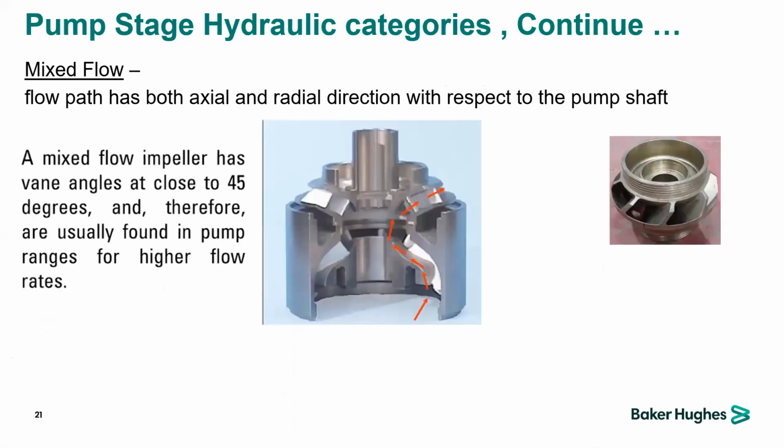Okay, with mixed flow, if you look at the pathway, it will be difficult to plug compared to radial flow. So mixed flow stages are recommended for applications where you are expecting plugging. When you are expecting sand plugging, wax, scale, paraffin, whatever deposits you are expecting or have experienced in your field, you have to use the mixed flow stages. Mixed flow stages handle almost 20% gas into the pump compared to radial flow, which we just said handles only 10%. So it handles almost double the value of radial flow.